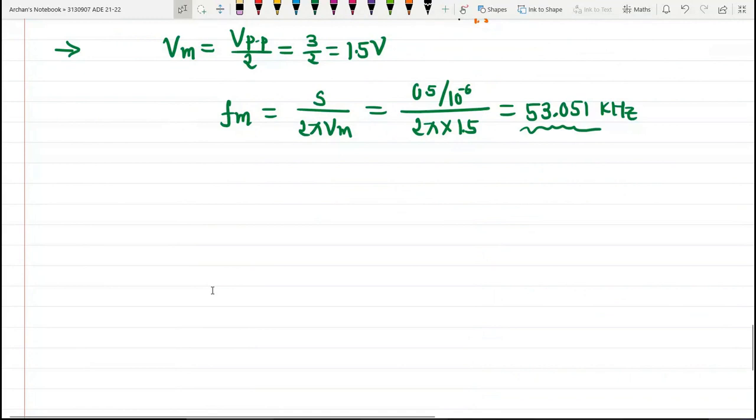So when these two transistors of the input stage are not perfectly matched, and this is the usual case. Remember, whenever we talk about the manufacturing of semiconductor devices, though the same manufacturer will manufacture the same device, be it bipolar junction transistor, field effect transistor, IGBTs or MOSFET, two semiconductor devices will not be exactly the same.